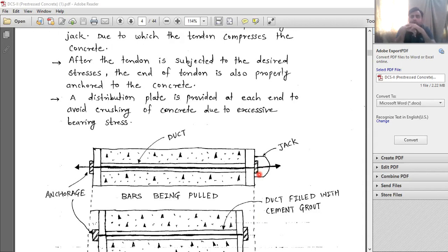Why do we provide the footing below the column? Why don't we directly raise the column on the ground? Because the column has a high length. Length is high as compared to its cross section. So when you directly raise that column on the soil, then it will try to punch through the soil also. Due to the heavy length, the surface area of the column is less as compared to its length. So the area of transferring the load becomes reduced. There are high chances of the column getting cracked due to the reaction from the soil. That is why we raise the column on the footing.